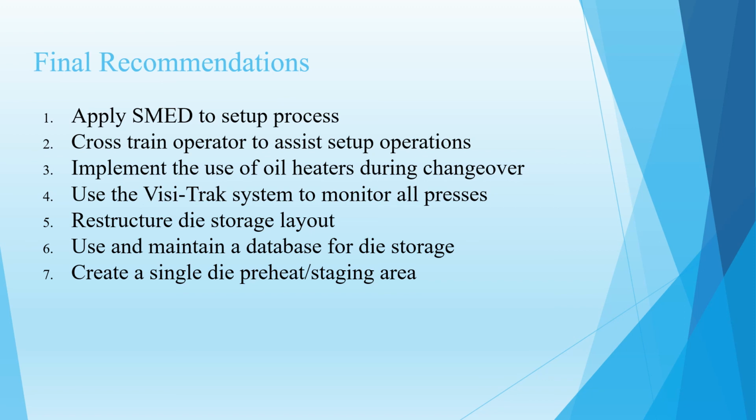Lastly, creating a single die staging and preheating area will reduce wasted time and movement of those involved in the setup process. With these recommendations, we believe that Cast-Rite can greatly improve the speed and reliability of their setup process and operations.